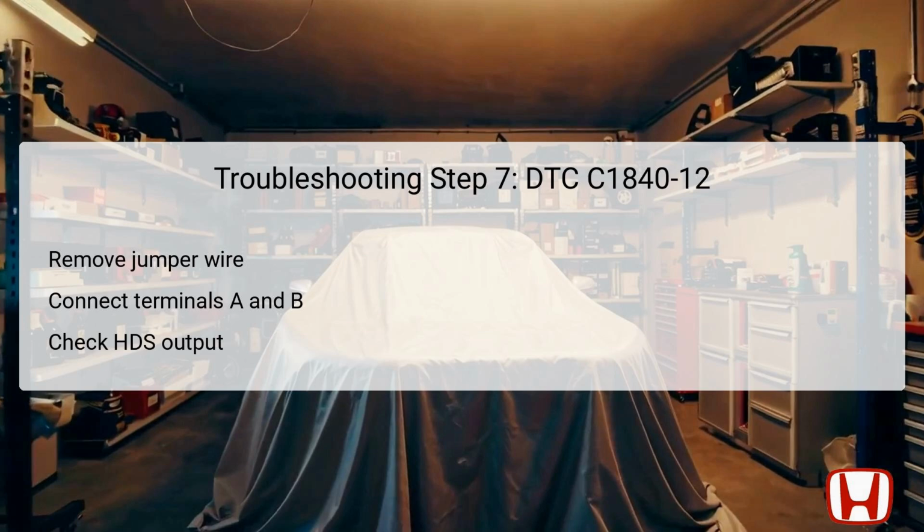If this voltage aligns with the specified threshold, the rear differential fluid pressure sensor is defective and should be replaced to resolve the issue. Conversely, if values are not met, it indicates the sensor is functional, and one should then transition to evaluating other wiring connections and components within the system.